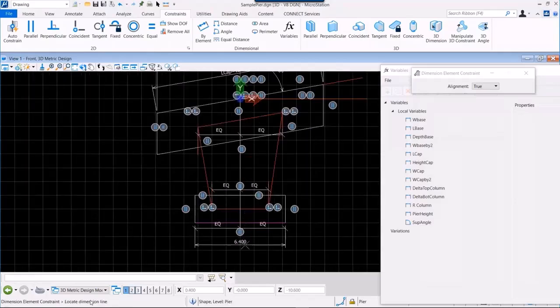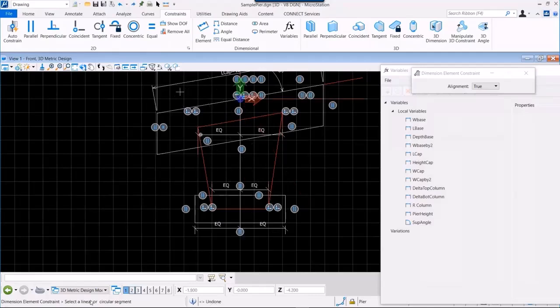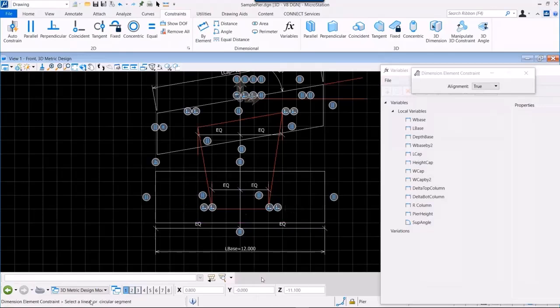So now if I define the constraints properly, when I change that dimension, my whole, in this case, 2D pier will react and move accordingly. Well, if it doesn't, well, you know that your constraints were wrong. Right? So this is one way to test. And again, I suggest you test step by step rather than finishing the whole thing and testing it afterwards. Right? So element by element, you can start dimensioning all of that.